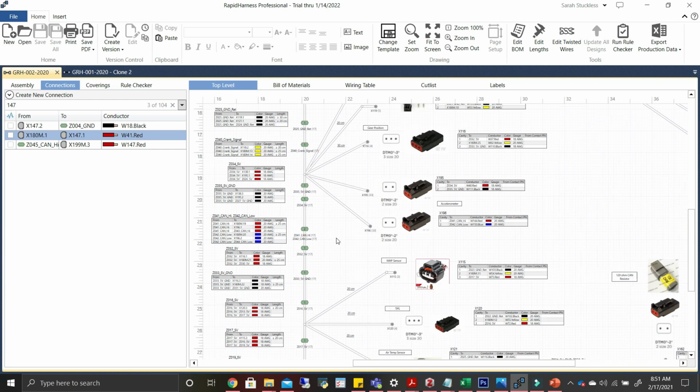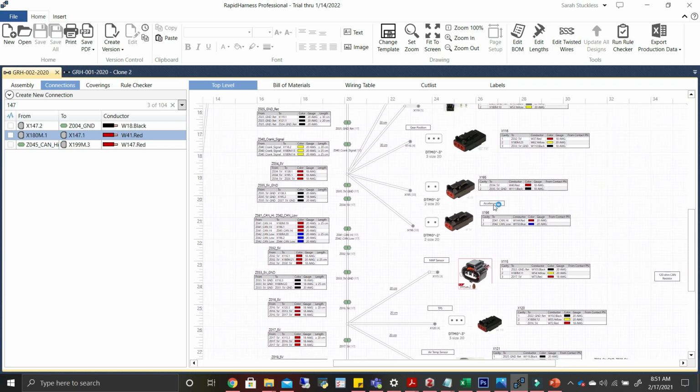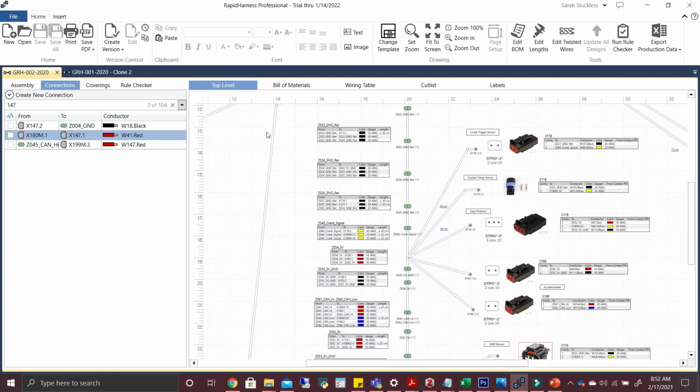And this little line here, which is basically to all the engine sensors. These little green things are the splices I mentioned. So just making sure that we don't overload everything. It will be 1 wire going in and then 2 going out to separate devices, or even to another splice even. A lot of these along the row are in a daisy chain circuit, it's called. And it's the best circuit to allow the current to flow easily along the devices and you don't lose any power. So that is the rear.